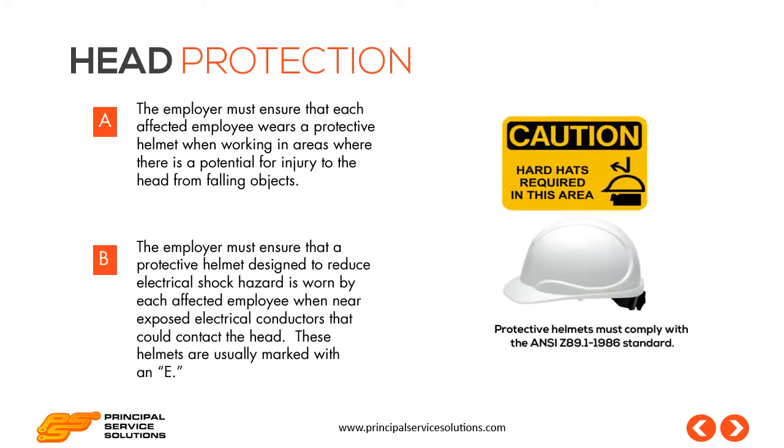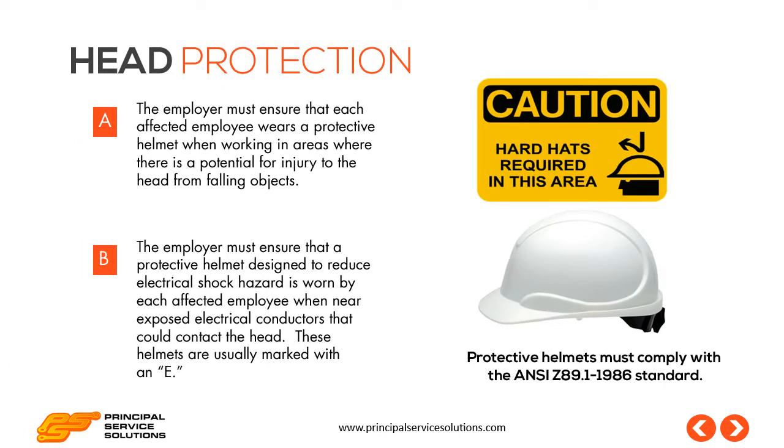The employer must ensure that each affected employee wears a protective helmet when working in areas where there is a potential for injury to the head from falling objects. The employer must ensure that a protective helmet designed to reduce electrical shock hazard is worn by each affected employee when near exposed electrical conductors that could contact the head. These helmets are usually marked with an E.